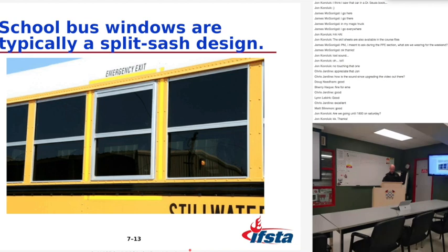School bus windows. Vertical posts between can be removed with power shears or reciprocating saws. They're made of laminated or tempered safety glass framed in extruded aluminum, split sash design. Provide an opening of approximately 9 by 22 inches, 1.5 total window area. Emergency exits are identified by hinges along the top side of the frame.